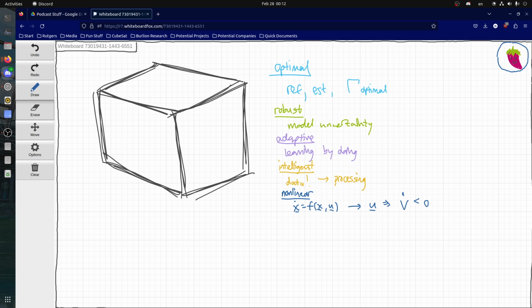It's usually easier to implement, right? People were implementing nonlinear control using op amps. It's really hard to do linear control with op amps, right? You can make like a single PID loop, but usually no more. For a nonlinear system, you could, in a very loose sense, literally hook up the output of a sensor to the actuators, and then assuming you have the right stuff in between, it would work, and it would work very fast, and it would in fact converge to zero if you had designed it properly.